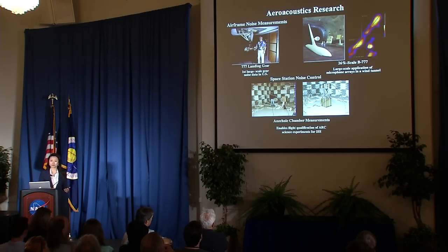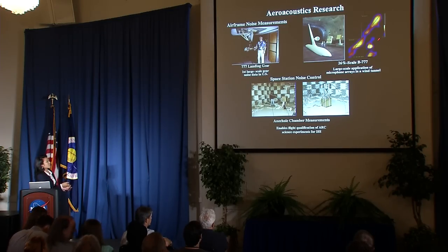So I would call it a sound picture. Once that picture is taken, you could superimpose this picture on the surface of the model, say here. Right now, you can see a lot of the noise coming from the leading edge, the slats, and from the trailing edge, the flaps right here.